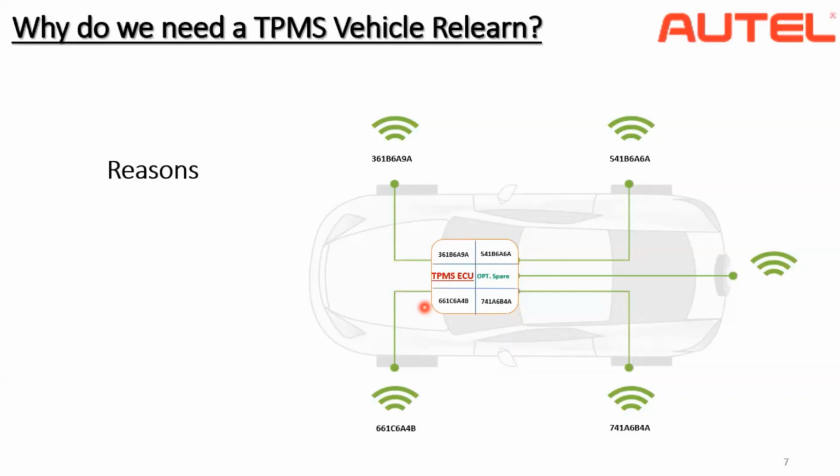So coming back to TPMS relearn, there are certain situations or conditions where we will need to perform a TPMS relearn procedure. One is replacing faulty sensors.